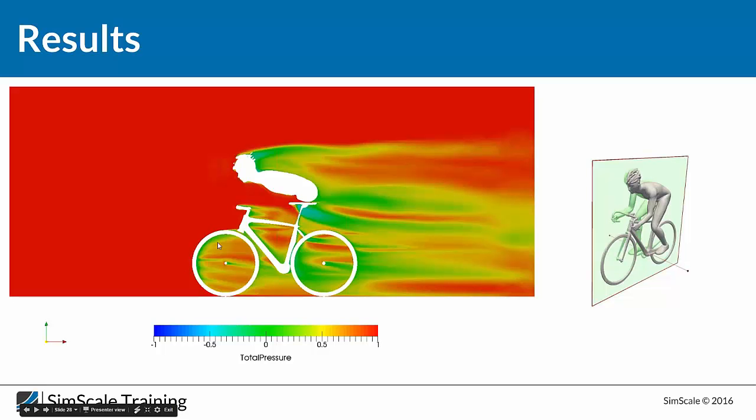And here we can see for the first picture, we have the thin wheel, and we can see that we have a large separation over here, and the wake is significant. Also the wake that is going to the back of the bike is quite significant, and the separation here is remarkable, and this will increase the drag of your bike and will reduce the performance of the rider because of the drag created by this tire due to the separation that I have already talked about.